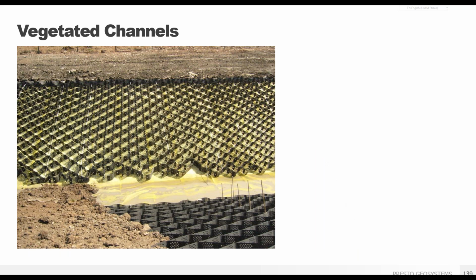Here's a technique tip for using the GeoWeb system along channel side slopes. Notice how the panels just cover the sides, not the channel bottom. The GeoWeb panels will allow for vegetation to grow up in both embankments, which will not normally be underwater. Notice the bright yellow liner below the panels. In this case, using the tendon anchorage system will hold the GeoWeb panels in place without damaging that liner. And you see the white tendons coming down slope towards the top of your screen.